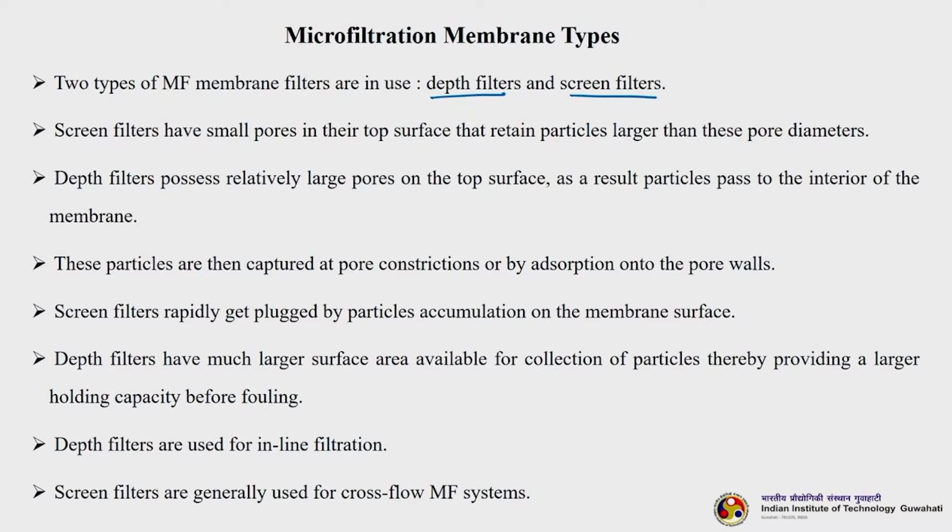Screen filters have small pores in the top surface that retain particles larger than these pore diameters, but depth filters possess relatively large pores on the top surface. Large pores means with respect to the screen filters. As a result, particles pass through the interior of the membrane, and these particles are then captured at pore constrictions or by adsorption onto the pore walls.